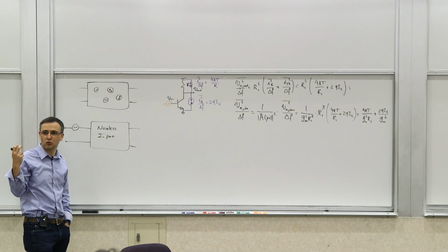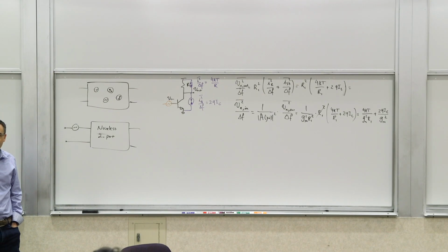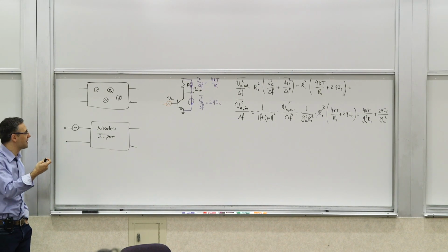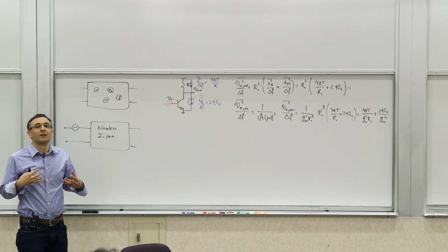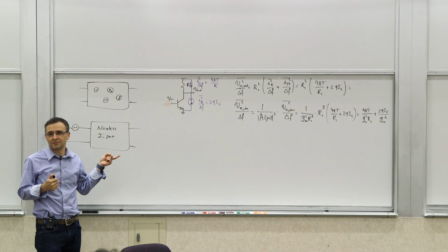It's a fictitious noise source, if you will. I'm emphasizing this because it's important to remember that when you're experimentally working with this, this noise is not physically there. It's just the equivalent effect. It's something that captures the equivalent of everything that's in there. So the reference for your calculation and measurements of noise is the output.